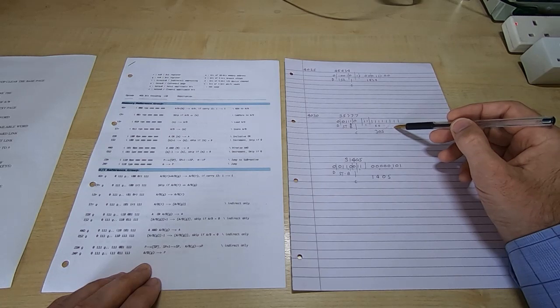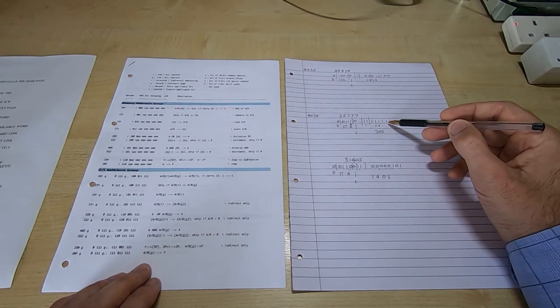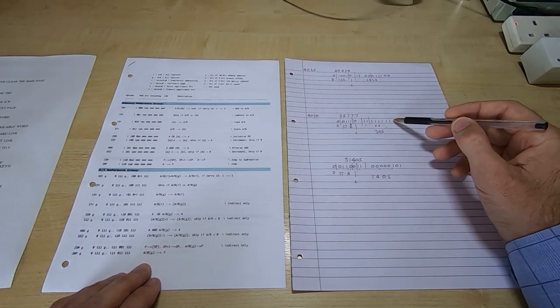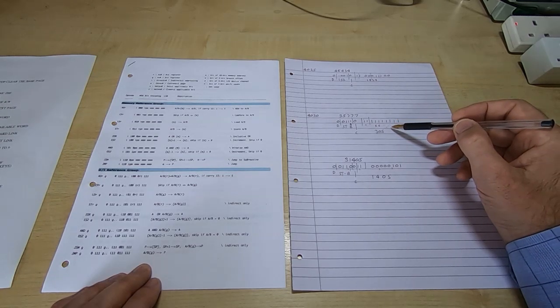There are some that are correct and some that are just totally wrong, and when they're wrong they're completely incorrect. So what I'll do next is capture the address bus that's going into the ROMs to make sure it's not reading a completely different address for certain values. I find it highly unlikely because of the nature of what I've been seeing, but I'll do that first. But it does look like this could be a major problem in that the ROMs have failed, or at least some of them have failed.